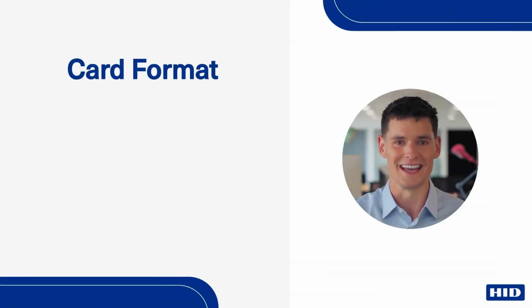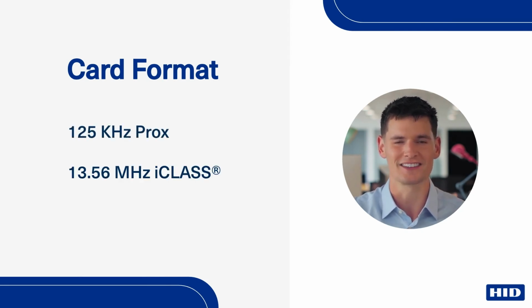The telephone company has maintained this format for many years and migrated to it slowly over the years, adding numbers in groups. Security equipment has similar format demands, however the security industry does not want the format known, and they often change the formats to keep the changes confidential. All specific card formats are identical in both 125 kHz prox and 13.56 MHz iCLASS cards. This ensures that any controller capable of understanding data from 125 kHz cards and readers will also seamlessly work with 13.56 MHz cards and readers.